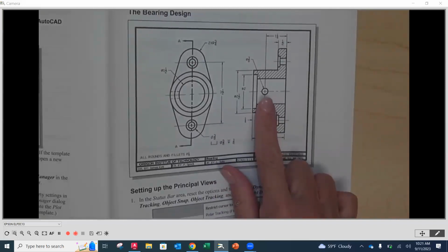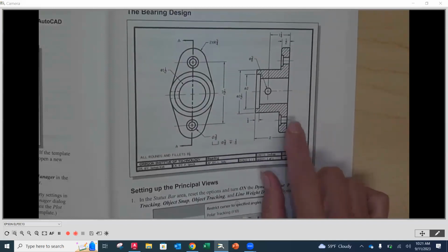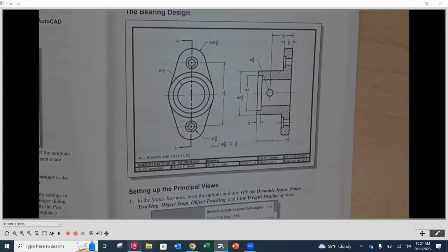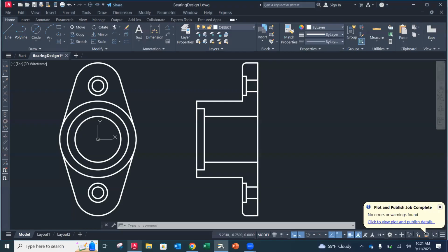Okay, we're going to put this hole in place now. So we know this hole is going to be along that center line and it is 1.5 inch up. So let's put that hole in. We'll go to AutoCAD. I'm going to do a center diameter. And now I need to specify, so I need to determine where it is and then do a reference. So I'm going to do a snap from. Now I don't have a center line here, right? But because this is one continuous line, the midpoint is in line with the center, isn't it, of this?